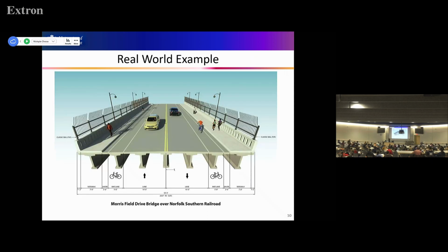So that is economical, right? Okay, and then this is a real world example. We need this deck to carry the passengers and vehicles, but these beams are the load carrying members. Okay, the load carrying member looks like this, and the majority of the sections are vertical shape, and we use a wide beam that has very high moment of inertia.